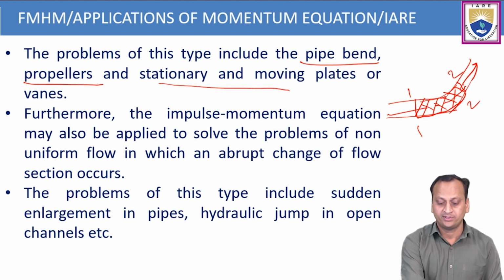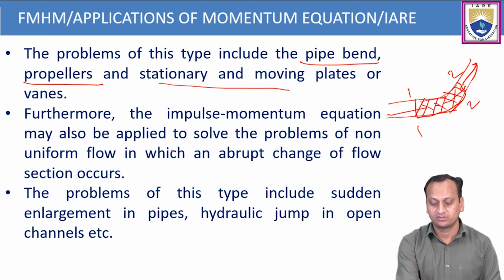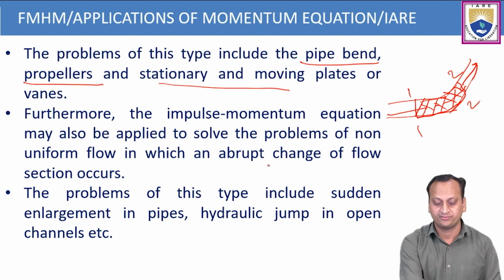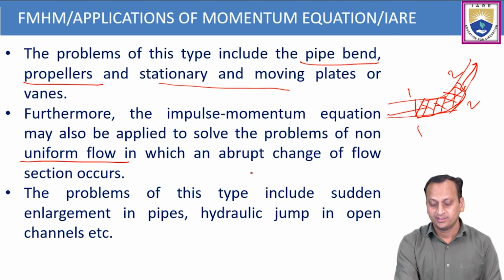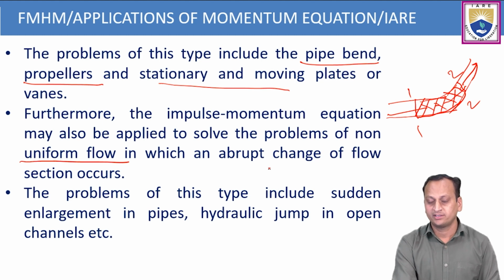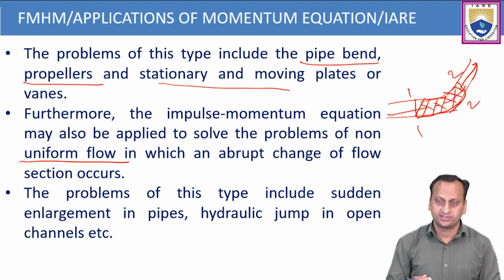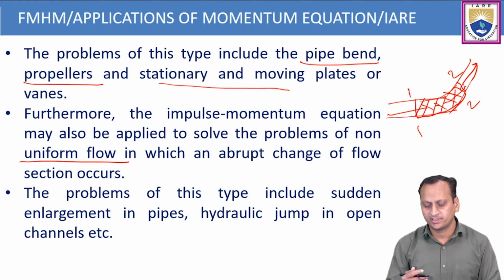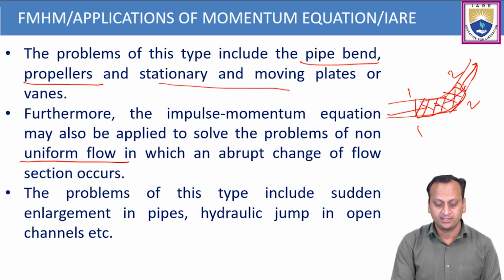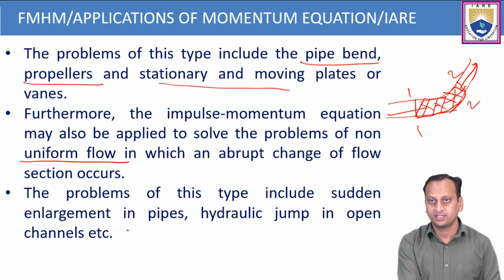So furthermore, the impulse momentum equation may also be applied to solve the problems of non-uniform flow, in which an abrupt change of a flow section occurs, where the velocity abruptly changes from section to section with respect to time. At every time, it may be changing every second. The problems of this type include sudden enlargement in pipes, hydraulic jump in open channels, etc.